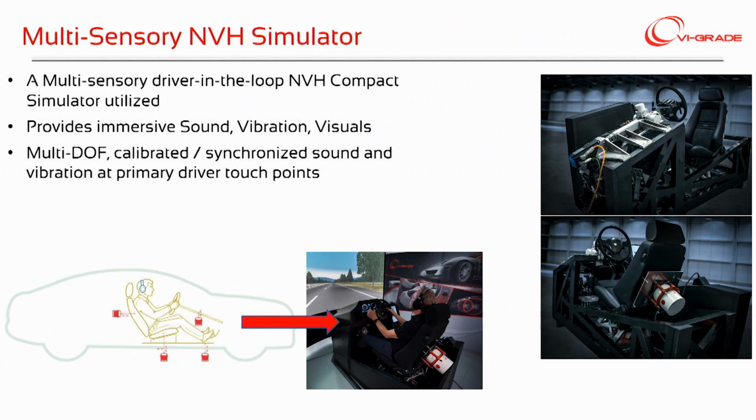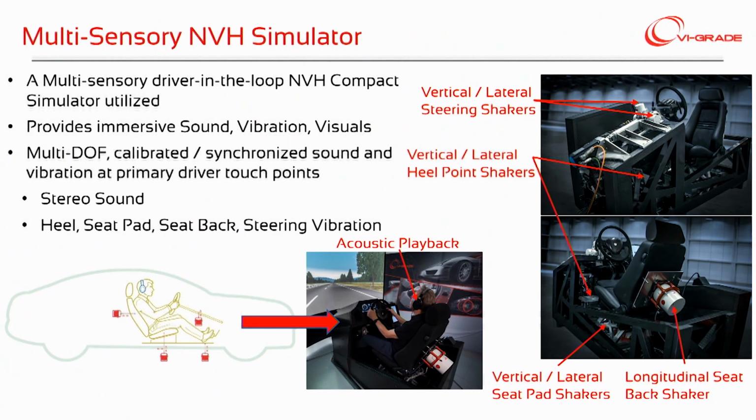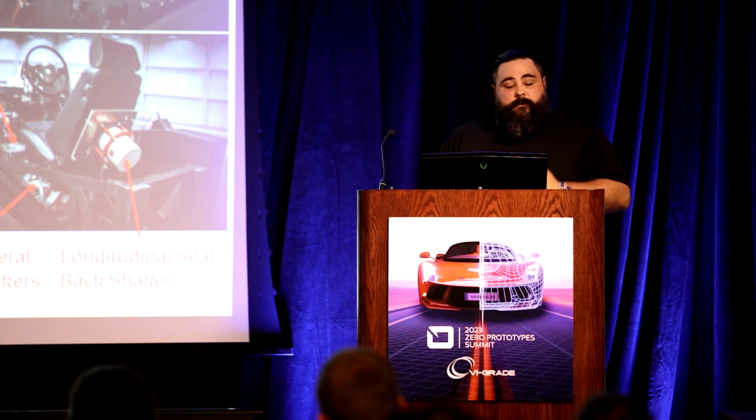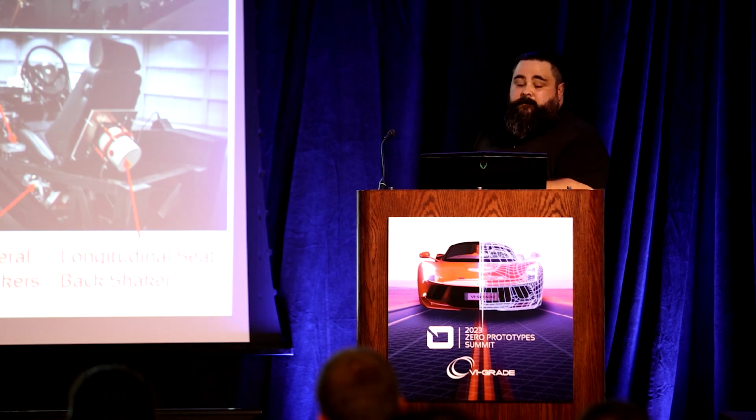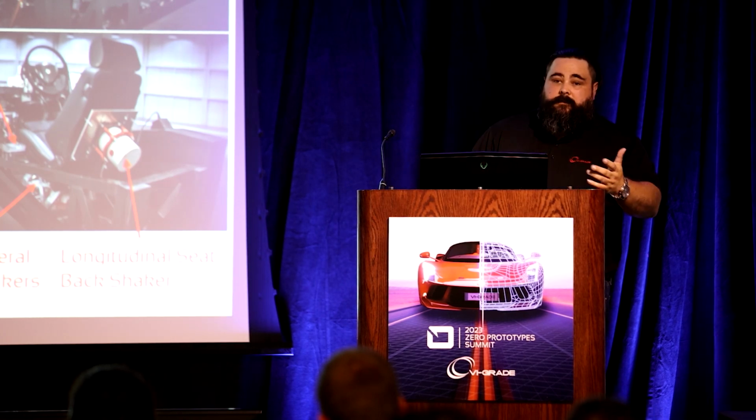So this is where the introduction of a multi-sensory NVH simulator, or just the compact NVH simulator, comes into play. It's basically a driver-in-the-loop simulator that provides immersive sound, vibration, and visuals. It is a multiple degree of freedom, calibrated, synchronized sound and vibration tool at primary driver touch points. So we've got stereo sound, and we've got various shakers at heel, seat, steering.